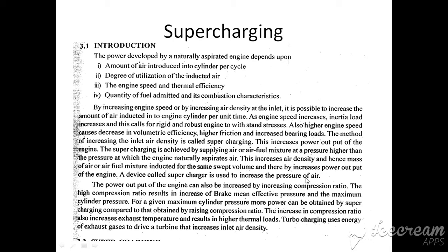So in today's high-tech automobiles, you have superchargers which develop almost double the pressure of the air, so that much more power can be developed. And in real life also, you can see a normal naturally aspirated engine, if it is generating 100 kilowatt, then for the same engine, if a turbocharger is put, it can develop 150 to 160 kilowatt, around 60% more power, without increasing the dimensions of the engine, just by introducing the turbo supercharger.